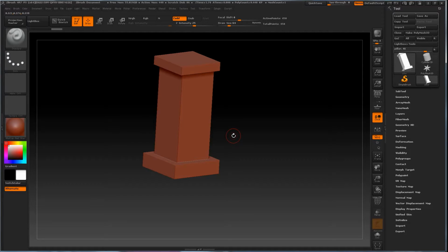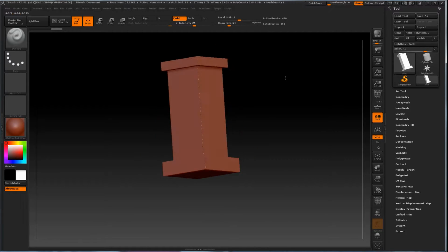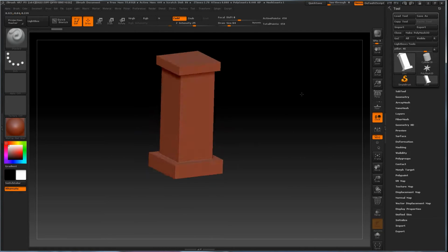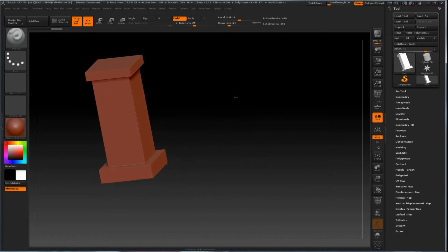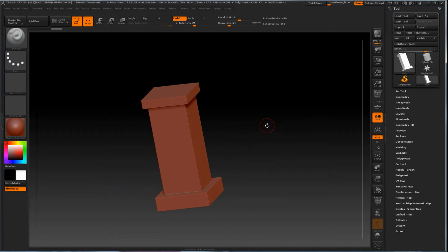So now you have a 3D object on your screen and the screen's not cluttered with anything else. For navigation purposes, if you want to rotate the screen, you would click not on the object, but anywhere outside of the object. So if I left click out here, I can spin the screen and look at this from whatever direction. If I want to pan, I hold the Alt key and the same left mouse button outside of the object, and I can pan the screen around.